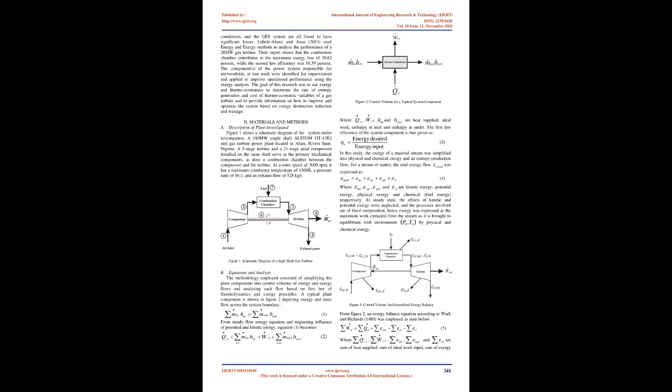Abade and Ugbokwe, 2017. Exergy analysis allows for the evaluation of energy degradation during a process, entropy degradation, and lost opportunities to do work, and thus provides an alternative approach to power plant improvement. Exergy can be lost because of a process's irreversibilities, and this provides a measure of the system's thermodynamic losses, as well as a way to locate and quantify wasteful energy usage. Wark and Richard, 1988. Exergy analysis gives a clearer picture of a process's true efficiency and is particularly useful for identifying the unit operations where efficiency improvements are most needed.